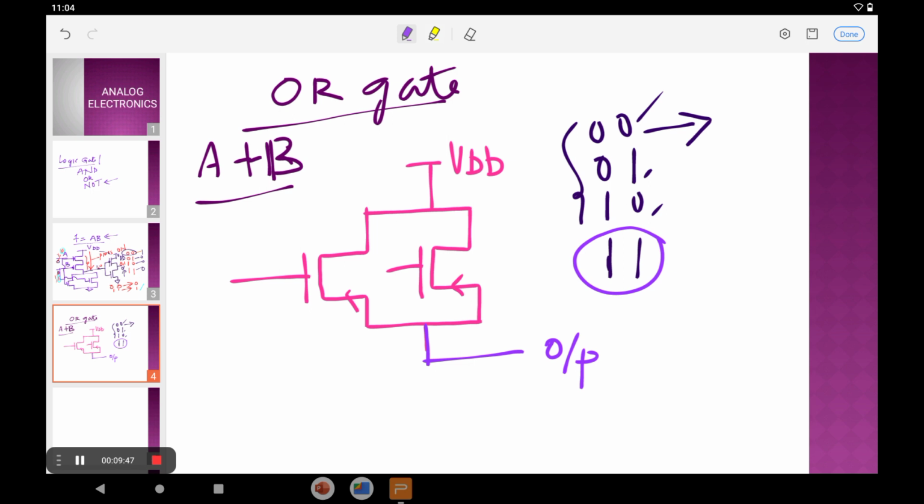Not valid means that whenever both logic inputs are 1 1, those PMOS transistors are going to be in the off state. So at that time we don't have a supply from VDD to the output side. That is a very important criterion. So the remaining pattern is very clear. Obviously, if you are connected like this, the remaining pattern should be opposite to this one.